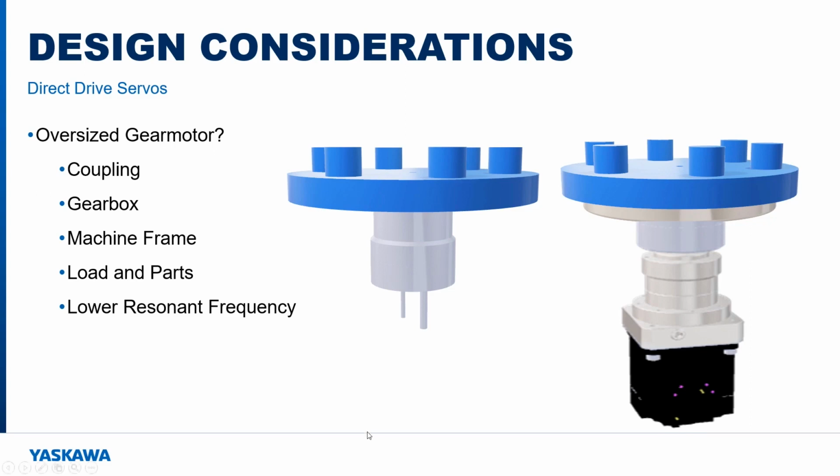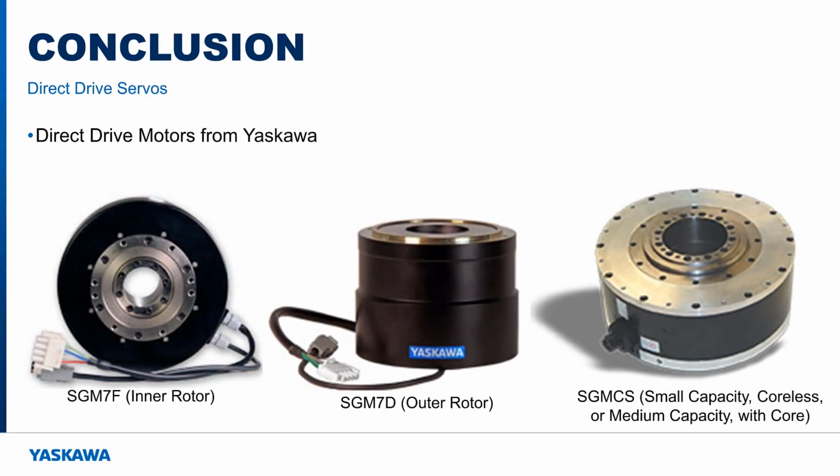And be sure not to exceed limitations on the load itself or on the parts and assemblies in motion. It is also useful to remember that while a larger motor on the same load results in lower inertia ratio, the resonant and anti-resonant frequencies will actually decrease and become more likely to cause complications with oscillation and tuning. I hope this gives you a solid introduction or review.